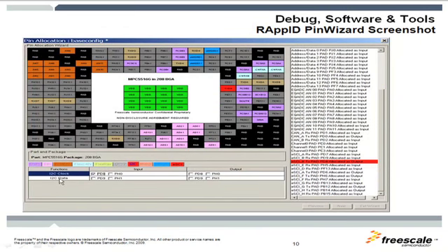It's hard to read perhaps on the screen, but we have I squared C. We can click: do we want it to be an input or an output, and which pin? And so as you go through all the different I/O modules, you can set them up. And if there's a conflict, it will holler and complain, so you can fix it, and it won't let you go forward. The result is a spreadsheet and documentation that you can then edit with your signal names.